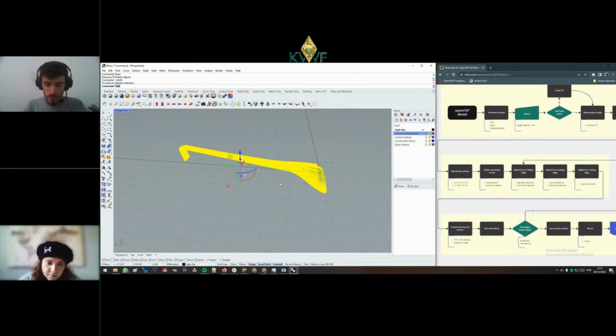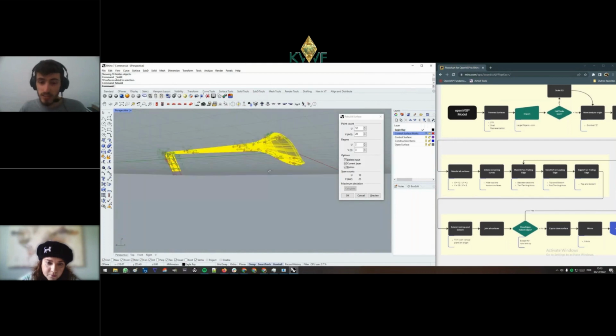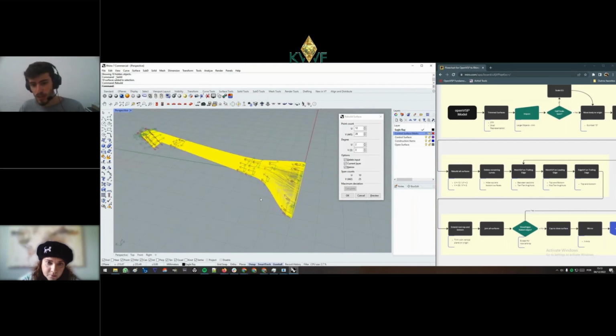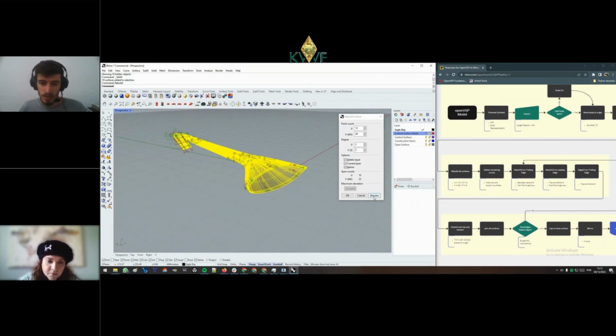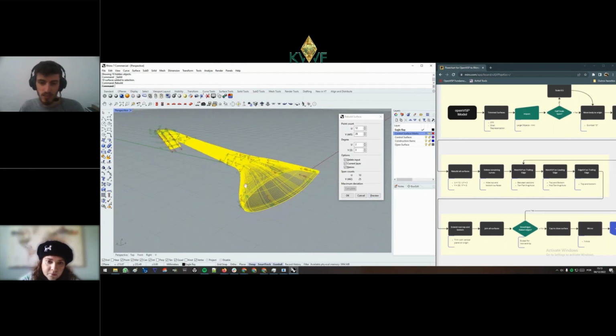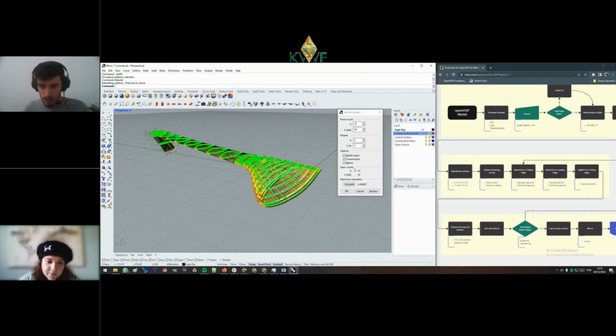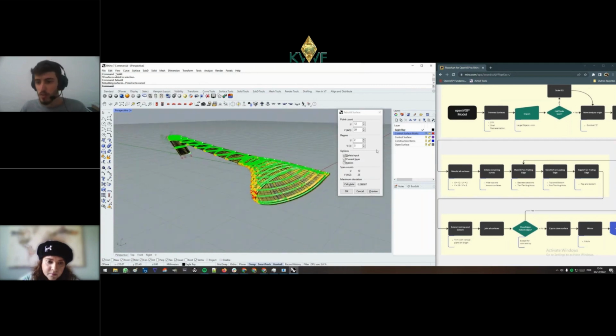This was actually one of the key steps. We had guidance from the people at Rhino. They showed us that our surface was too complicated and this makes it harder to work on the body. So this rebuild step is really important. We went through a couple of configurations here, but this is the one we found that worked well, mainly the second and third degree for the U and V curves.